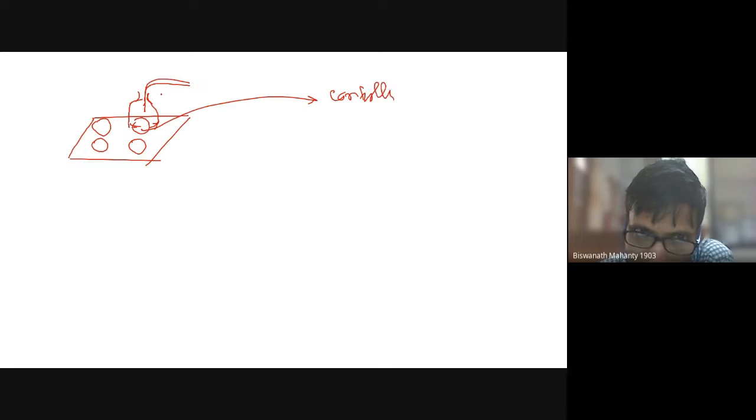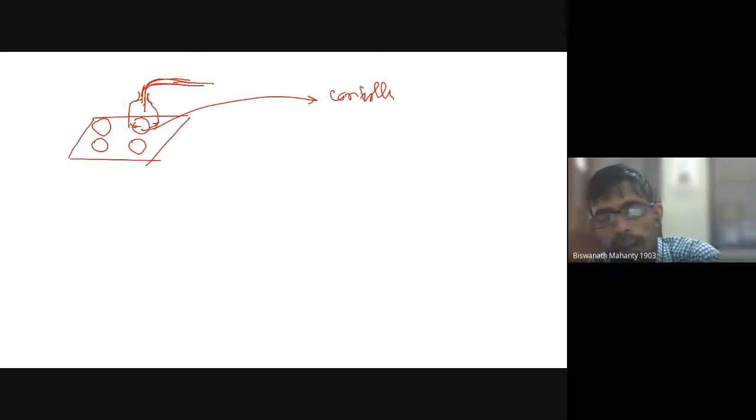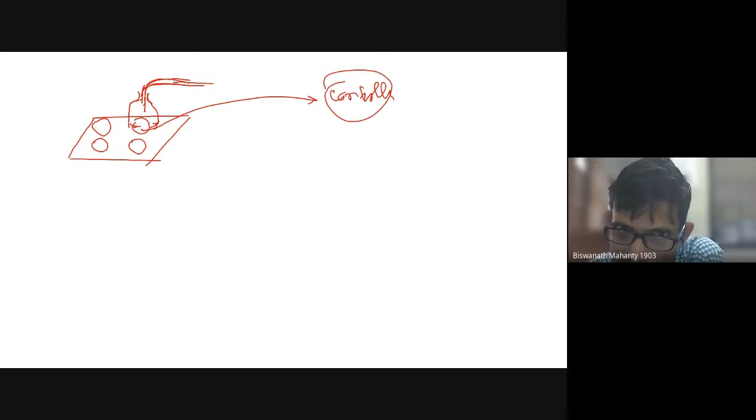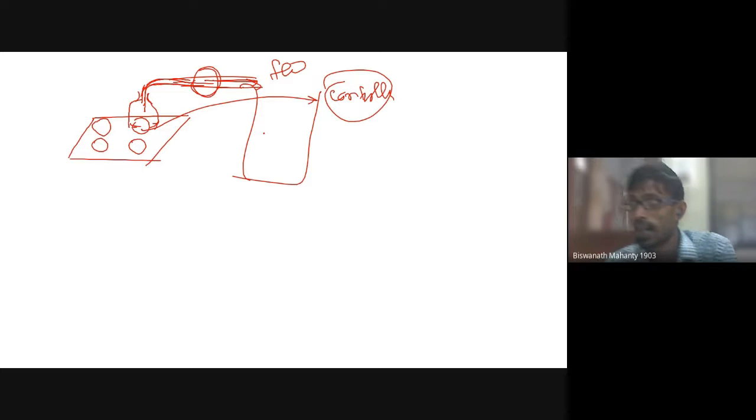It means we can measure how much liquid has been discharged or delivered. Based on this input, it knows that after 5 minutes this much weight is lost, so it can give you the idea of the flow rate. The pump is already running, pumping liquid into the fermentation broth, but we can also have online weight measurement devices which measure directly. The total weight is known, and as weight is lost we can calculate the weight loss.